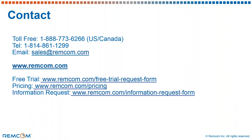There's a question about whether there's a way to automate beam switching or beamforming in Wireless InSite. We have techniques right now. The capabilities that we showed here for beamforming, as an example, beamforming to the mobile device as it's moving through the cell, while also beamforming to 8 other devices, these are prototypes of capabilities that are in development for a future version of Wireless InSite. Those aren't available yet. At the moment, our main output from the MIMO capability is the H matrix, but once the beamforming capabilities are available, the intention will be to release those within Wireless InSite.